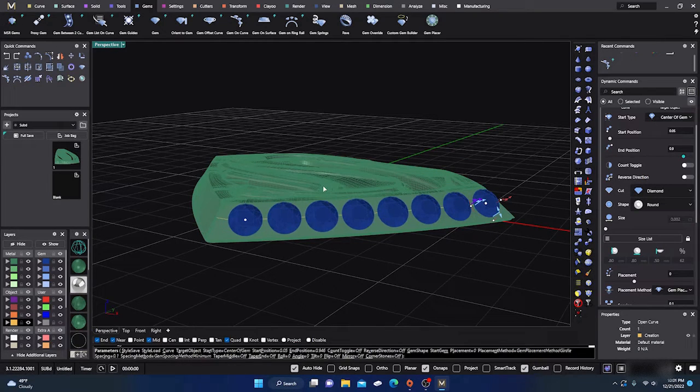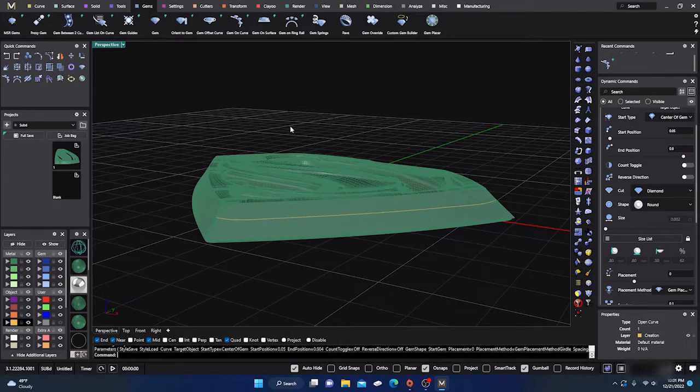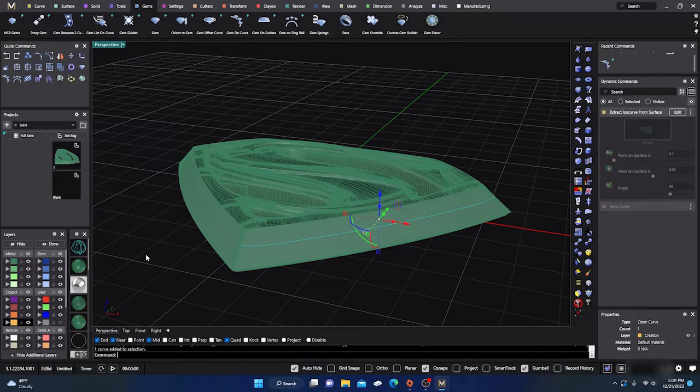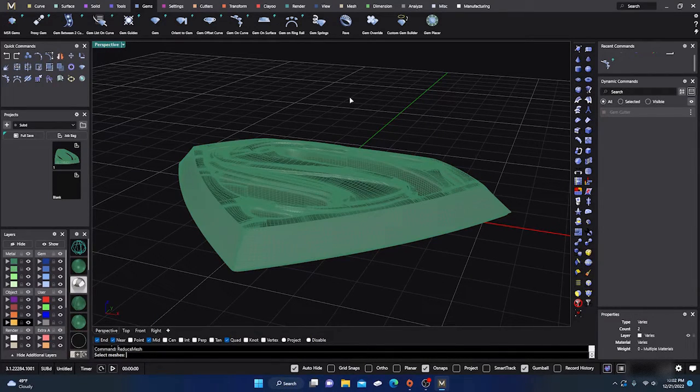The lower the better, actually. But let's go ahead and get rid of these, right? And I'll take that yellow and get rid of it too. Actually, you can try and go in and do another reduce mesh, but probably shouldn't. It's not a mesh; it's a poly surface now.